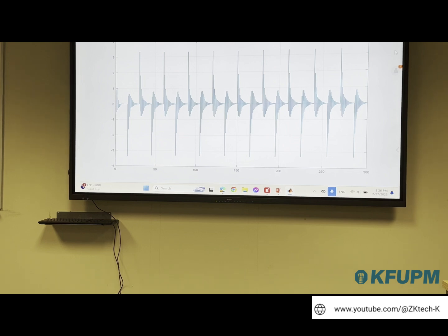Can we consider this as chattering? It's not chattering, because chattering is normally on the state, in the output. This is oscillation in the controller. But this will affect our actuation. So basically, if you have an airplane, you will see the flappers doing this all the time in order to keep you stable. So what you see at the output is a very nice signal, and your airplane does beautifully well. But in the back, this is happening in order to keep you on this level. You understand what I'm saying here?